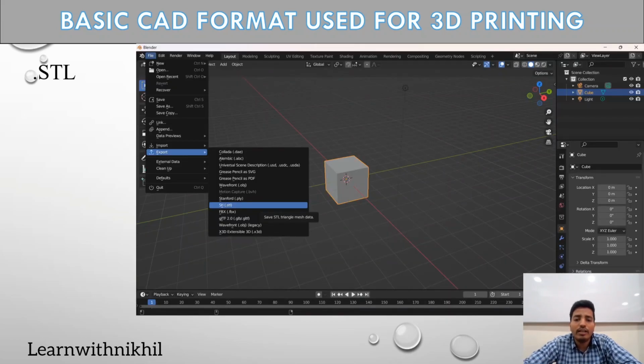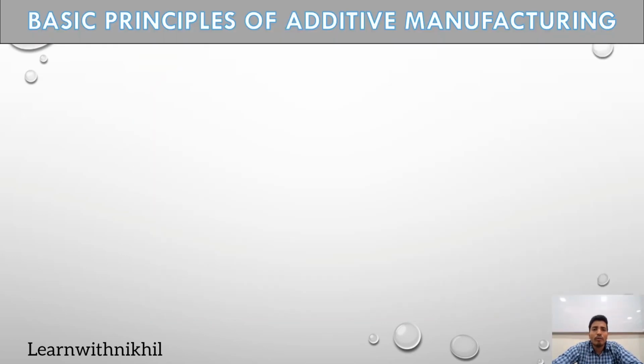STL is a widely used CAD format for 3D printing. Whatever CAD formats you have, you can see here various CAD formats. This is a screenshot of Blender. It can convert into various CAD formats, and for 3D printing we are using STL. This STL file is uploaded into the slicer software, and then you get the G code files. So STL is widely used for 3D printing. Many more STL formats are there, but these are the basic and widely used ones.